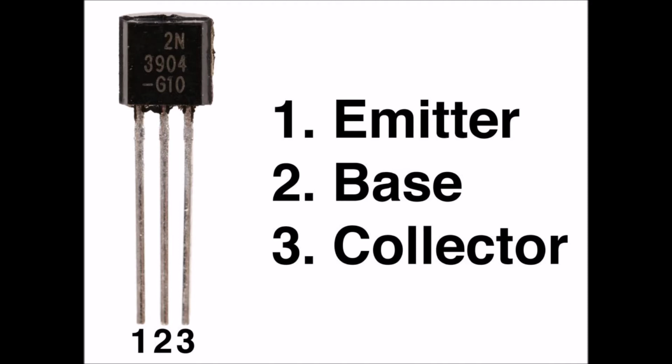Figure 22.8 shows the alpha cutoff and beta cutoff frequencies for the hypothetical transistor on a graph of gain versus signal frequency. Note the scales of this graph are not linear and that the divisions are unevenly spaced. We call this type of plot a log-log graph because both scales are logarithmic rather than linear.